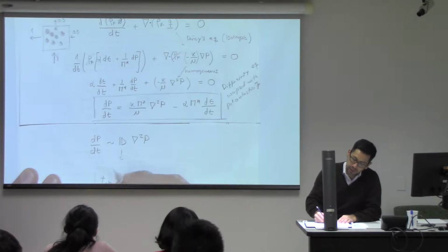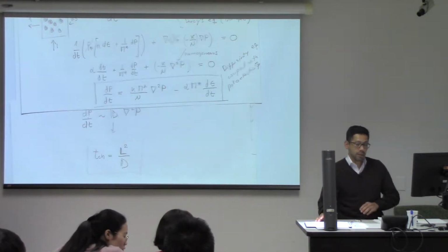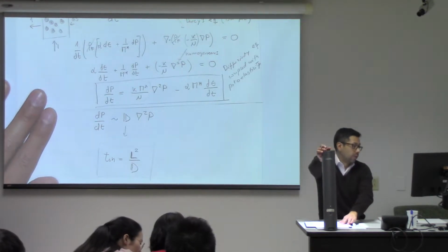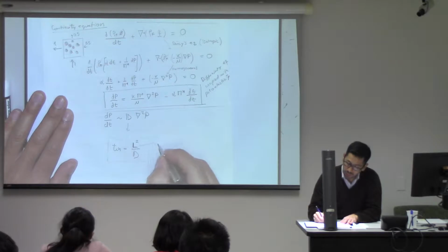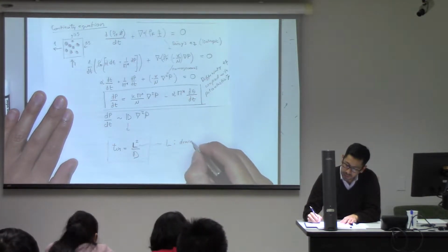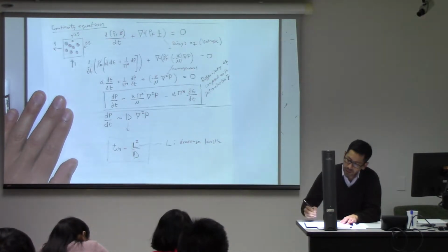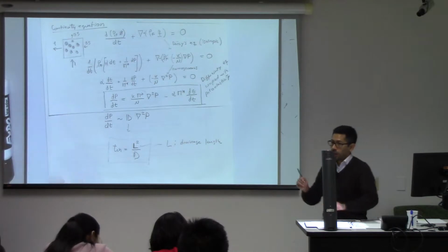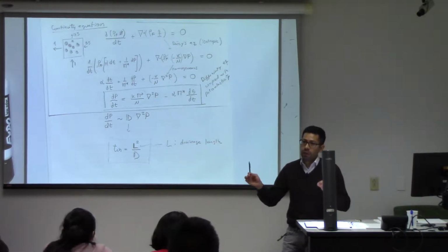And this is going to tell you how much time, more or less, it is going to take for that pore pressure to change according to, in this case, what is known as the drainage length. That drainage length, we're going to go through some examples today. It's the characteristic length of the problem.